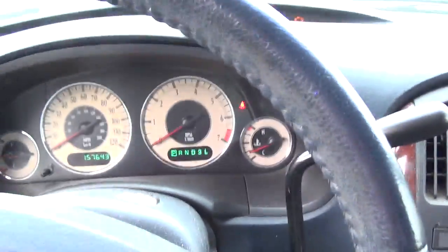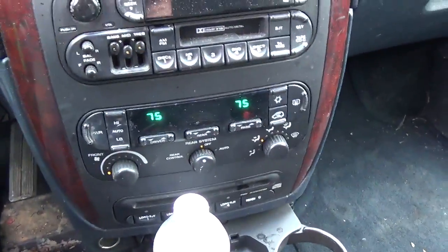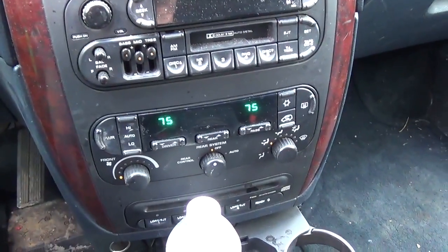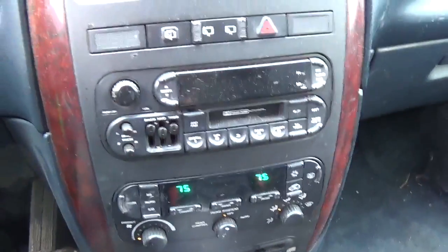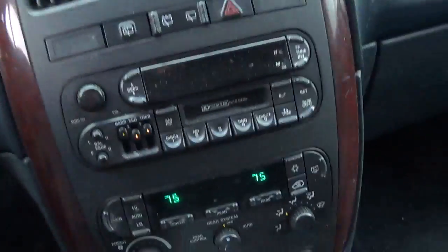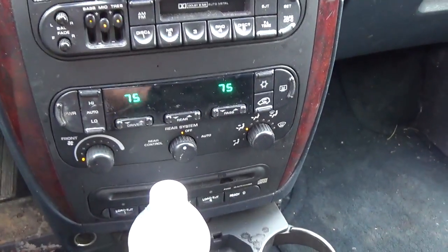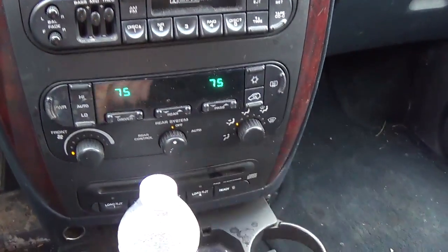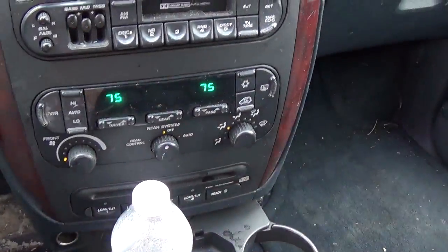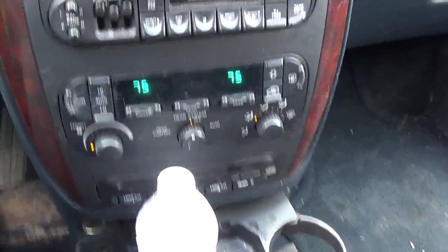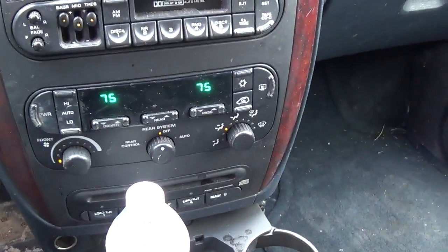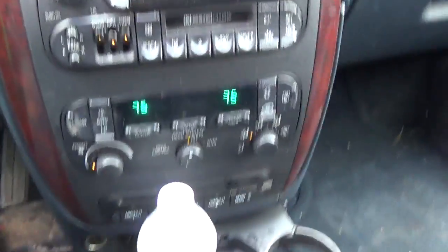So first plan of attack here, I'm going to pull up a wiring diagram and see what the easiest thing to check is. Usually I start either at a blower motor relay or at the blower motor resistor, depending on what's easier to get to. Because on this system, it's the automatic climate control, so instead of just a regular resistor, there's a smart module. This thing sends a pulse width modulated signal to the module, and that controls the current going to the blower motor. So it's kind of similar to a Chevy truck that I've done recently. Maybe I'll link to that in the description. So let's get to it.